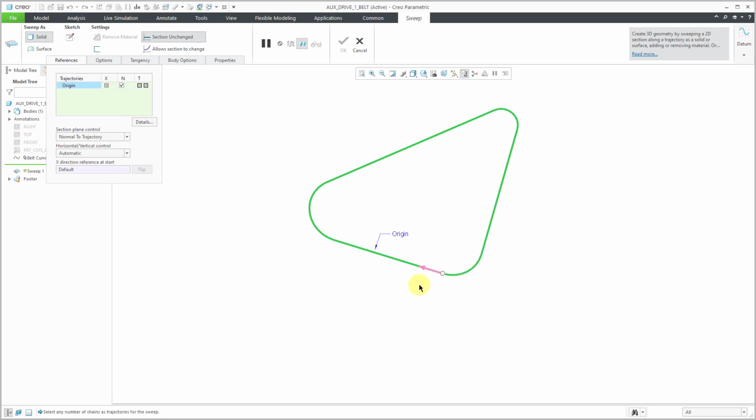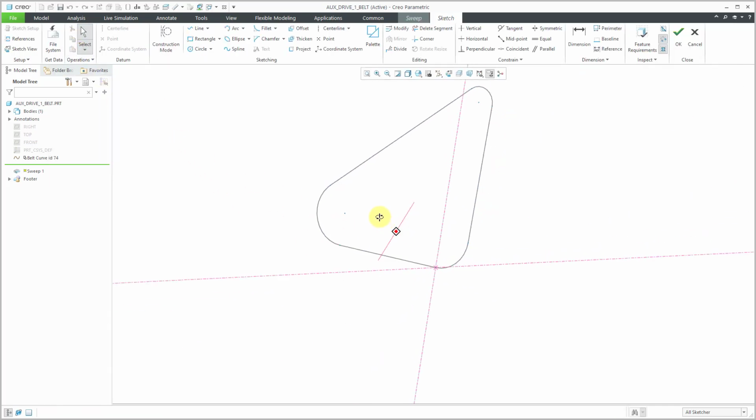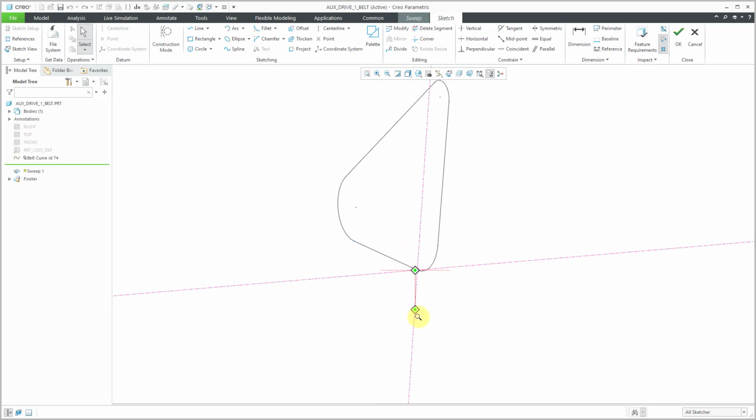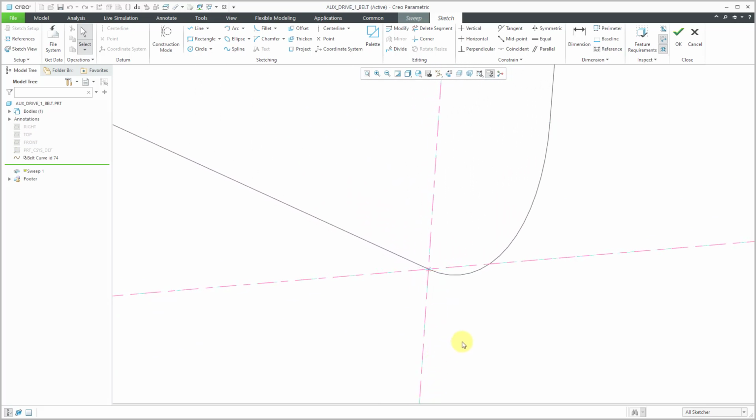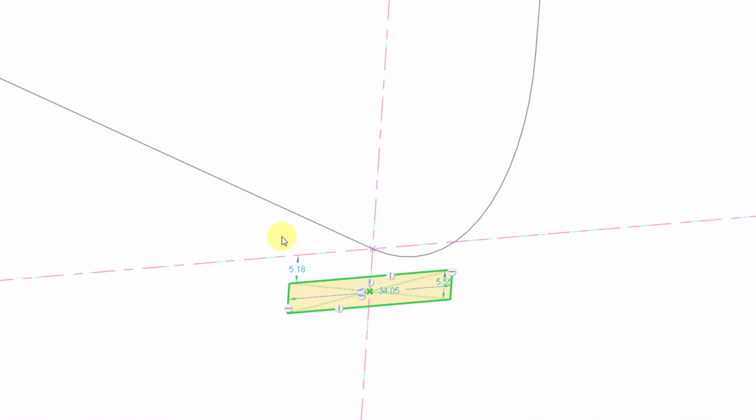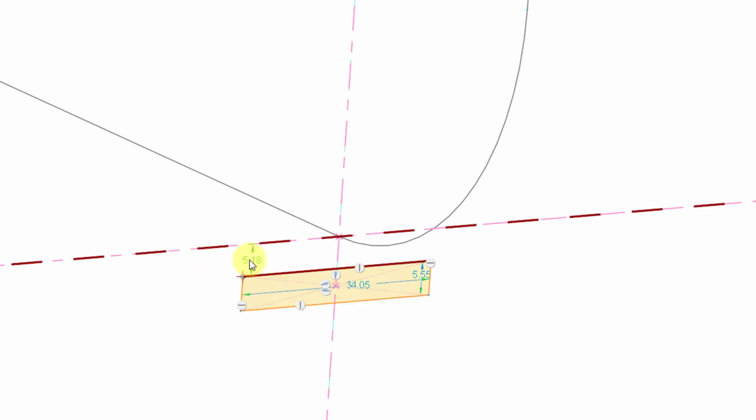And here we can see the direction that the feature is going to be created. I am fine with that. Let's click on the sketch button. And the sketch in this particular case, for the base of it, it's just going to be a rectangle. I will use the drop down and go to the center rectangle command and drag it out about yay big. Then for the dimensions based on the other part, this is going to be a value of 1.6.